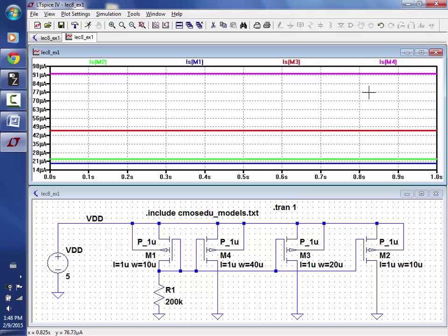Is it possible to... The hand calculations in nano CMOS are tough, so that's why we generally use charts. So a plot like in chapter 9, figures 32, 33, 34, and you get the charts. And when you go to a company, they have a manual that describes the process. The manual will have all the charts, so you don't do hand calculations from the square law stuff we're doing. It's more reading off the charts what the values are for the parameters and then simulating.